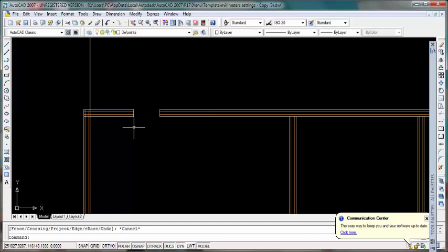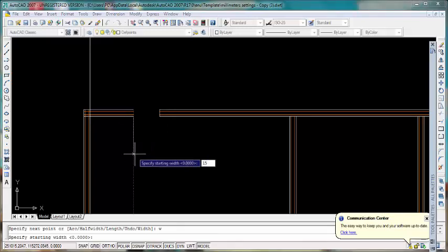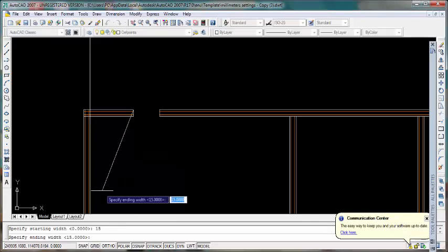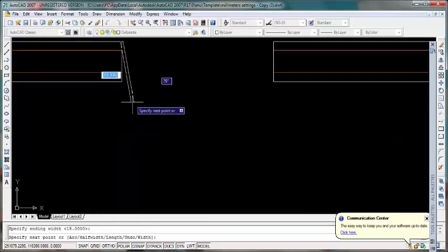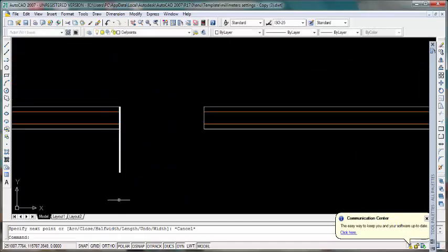Now this is where we use a polyline. The polyline is this shape. See it like you've got an anchor, and you can specify start point. See the start point, and it's asking you for the width. Click enter for the width, and let's say you want it to be 15 millimeters thick. Same thing for the end, we want it to be 15 millimeters thick. And that's it. See, we have something this far.